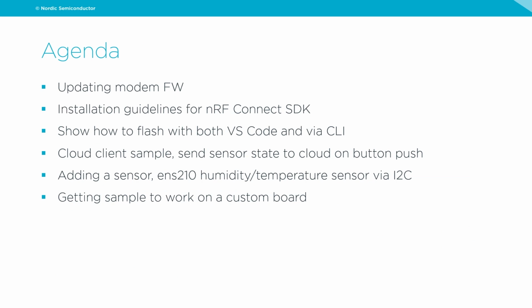Okay, so just a quick agenda. I'm using the nRF9160 development kit together with an ENS210 temperature/humidity sensor. Basically, what I'll show you is how to go from getting started, so updating the modem firmware first off, then how to install nRF Connect SDK, and how to flash with nRF Connect for VS Code, also via command line interface.